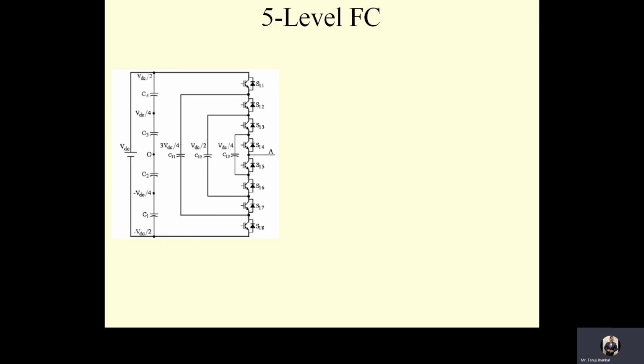Now this figure gives one leg of a 5-level inverter. The voltage across the floating sources or flying capacitors naturally evolves to the expected value in a closed loop system or open loop system. In other systems, these capacitor voltages have to be kept constant by ensuring equal charging and discharging of these capacitors over the switching time period.